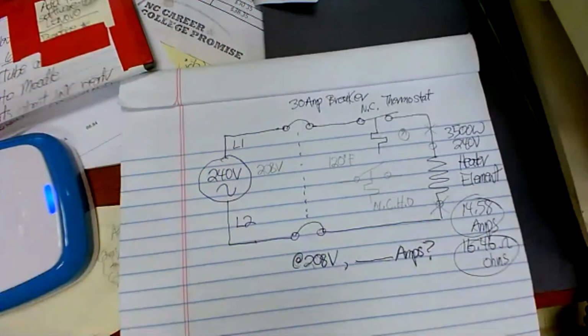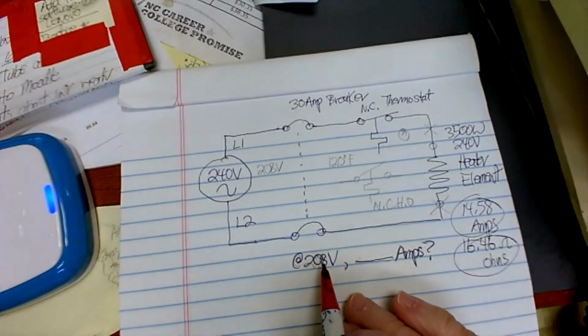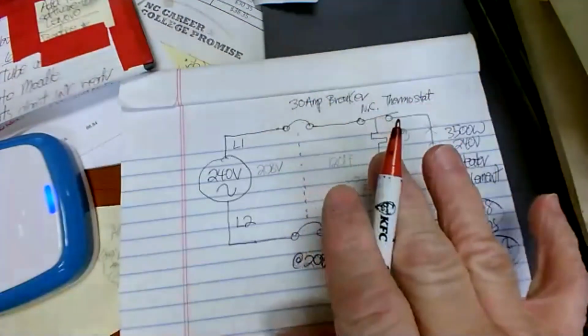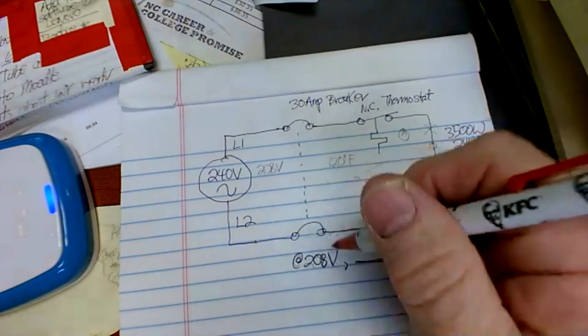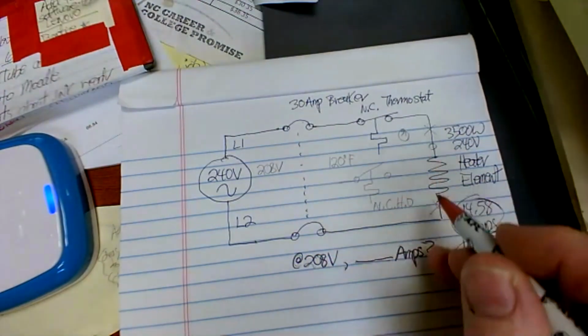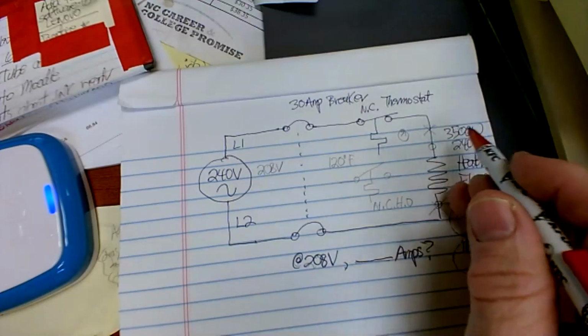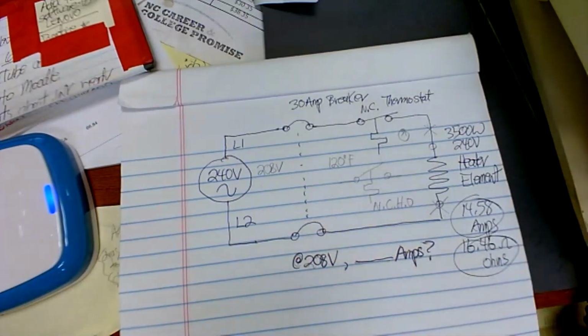That clear now? What is the watts? We don't know what the watts is going to be. We're going to calculate that, because look, the wattage is going to drop. I want to know what the amps is at 208 volt for this heater element. But you can't use that wattage, because the wattage changes when you drop the volts.